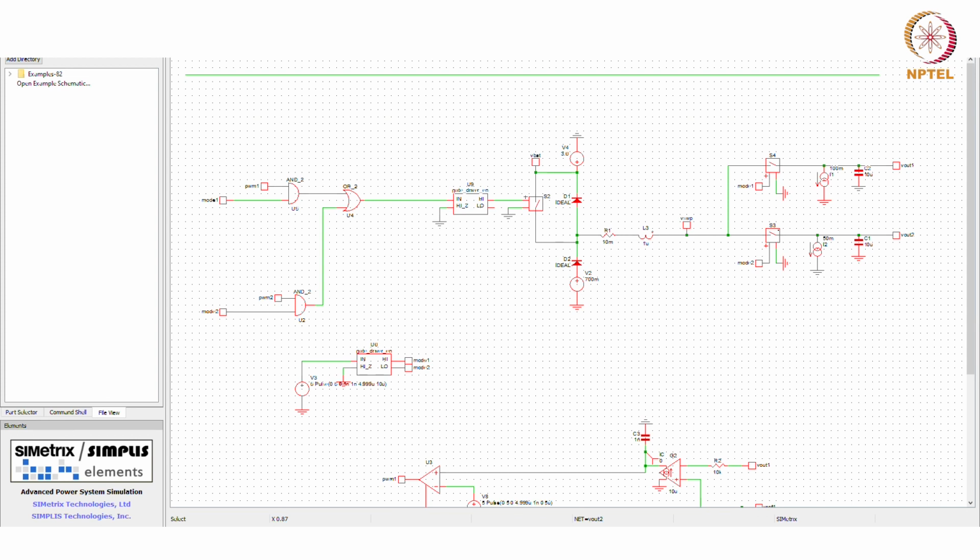When I say cross regulation, that's what it means. Cross regulation means one output tries to disturb the other output and it will never regulate actually. It will go out of regulation. So you have to take care of that, and that is usually taken care of by making sure that whatever current is supplied here, you have to supply that here too. So that balance you have to maintain. If there is an extra current, you have to throw it out by adding a freewheeling switch here.